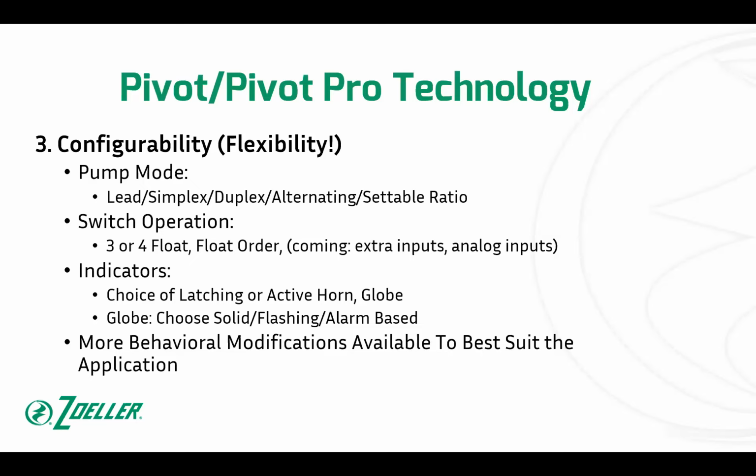They're probably rare, but there are applications where either where you're pumping it can't take that much flow, or hopefully this isn't the case, but sometimes I know people have used it because they haven't gotten enough power to the panel. It's only enough power to run one pump at a time. So you don't want both pumps turning on. So there's some real uses for that.